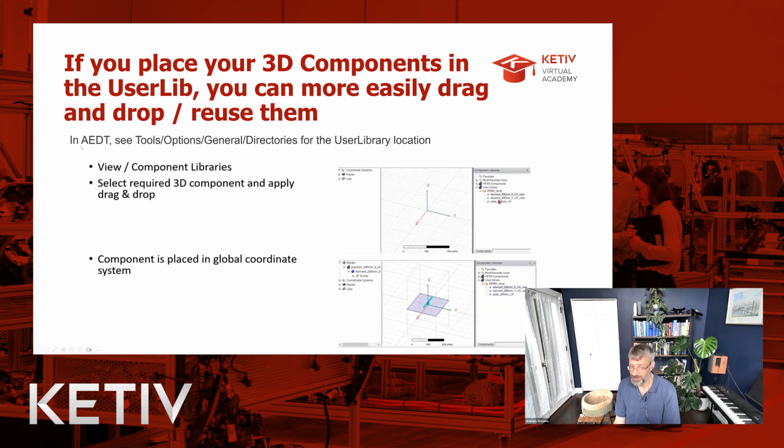And to find that location, you just go to Tools, Options, General Directories in AEDT to get the user library location, so that you can know where to place those 3D component parts.